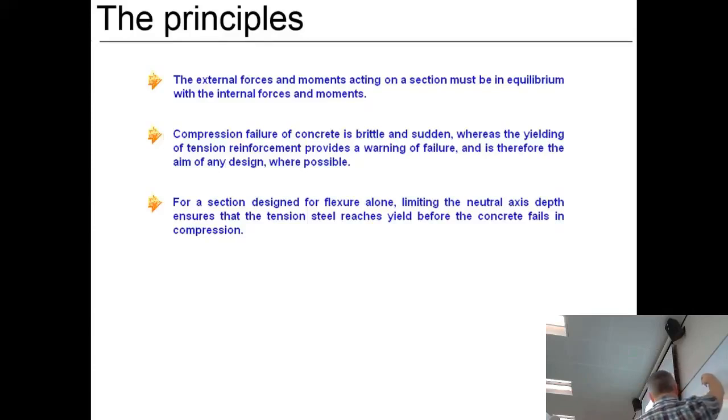Then with the concrete, you can sort of choose which stress of concrete you want to use and the dimensions. And you'll see that the formula is very much built upon the width B, and you've got the depth, which is D, which goes from the top to the reinforcement bars. And concrete above the neutral axis is considered for compression, so we will use that.